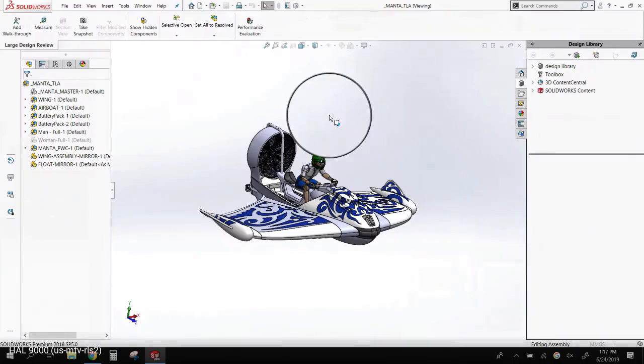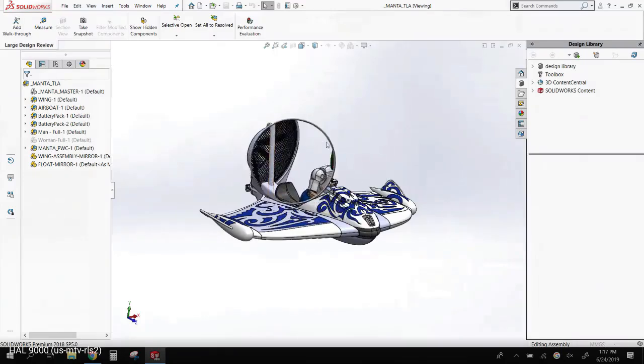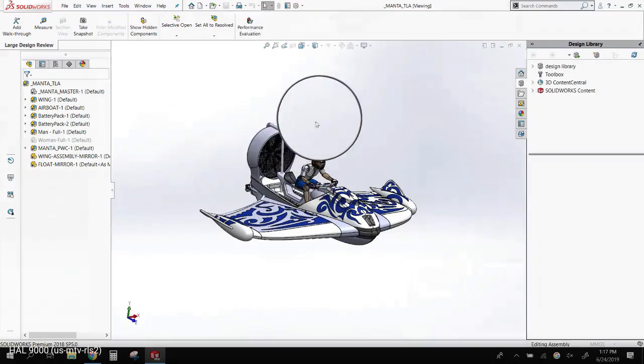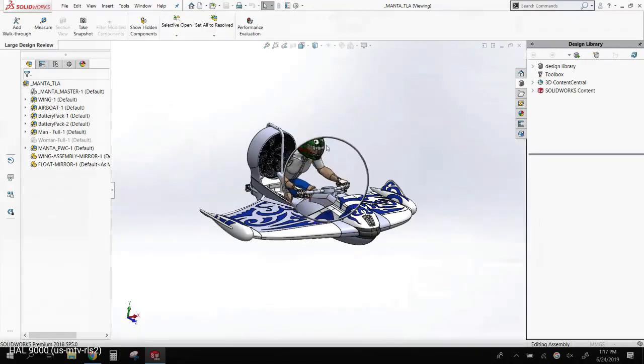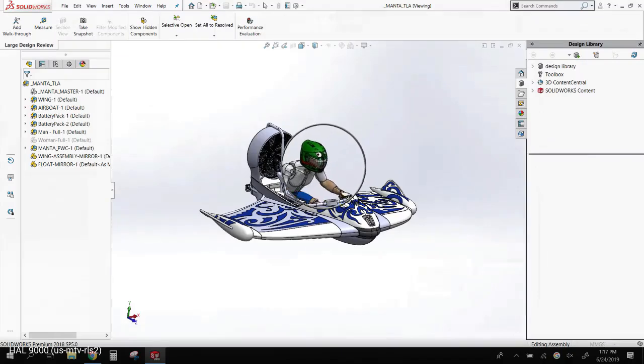Right next to the F is a G key. Brings up this little magnifying glass. It's kind of a pain to move this around because what you do is you move your mouse and when you hit the side of the magnifying glass, it moves it over. But I'm going to talk a lot about the Control key because it's one of the most magical keys on the keyboard. If I hold my Control key and I hit the middle mouse button, I can move this thing much easier than bumping the edges.